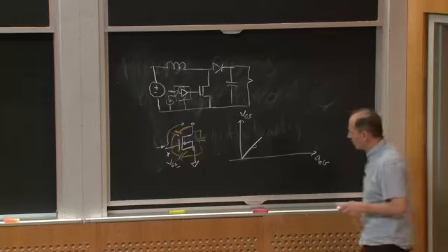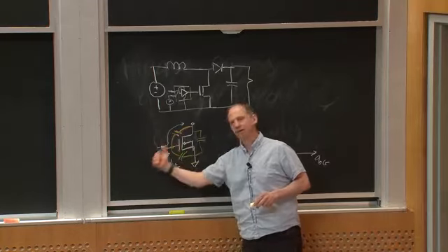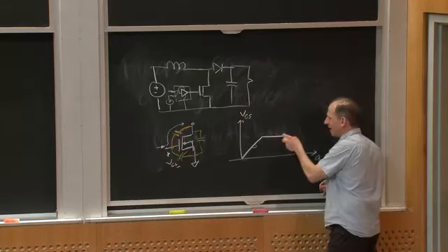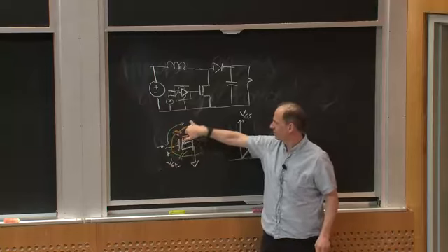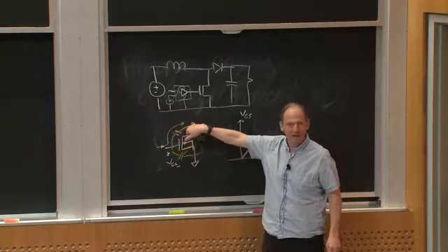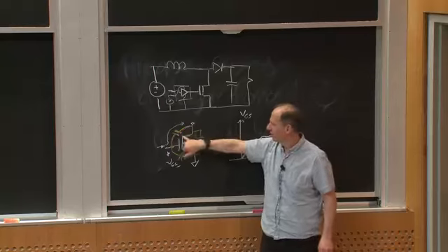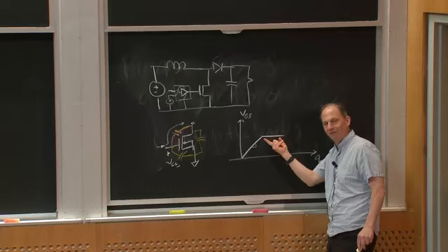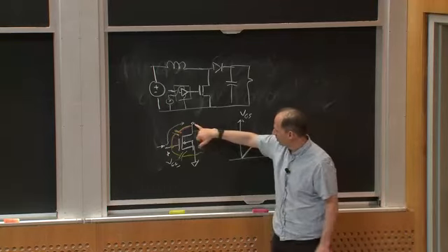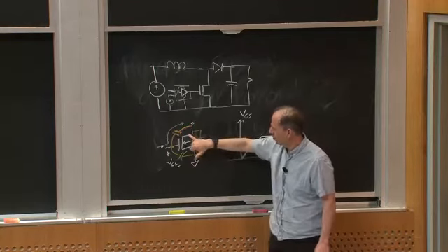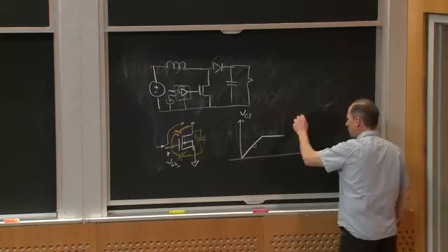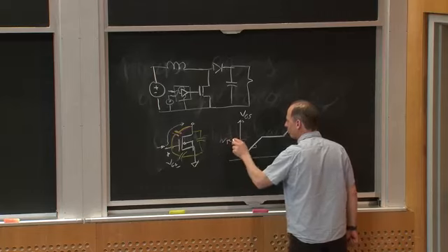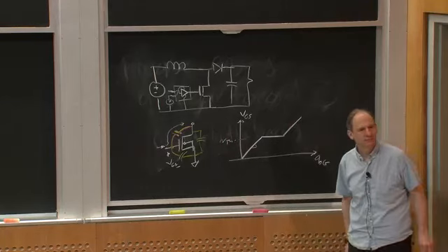What that means is I'm pumping charge in here, but the gate voltage isn't going up appreciably. It just sits flat, and all the charge I'm pumping in is basically going to drive the drain down. So this capacitor suddenly makes the equivalent capacitance I'm driving at my gate very large. Eventually, once I've pumped enough in, this node comes down to close to ground, this voltage ceases changing, and then this goes up like this. So this happens somewhere near VTH, the threshold voltage of the FET. Does that make sense to everybody?